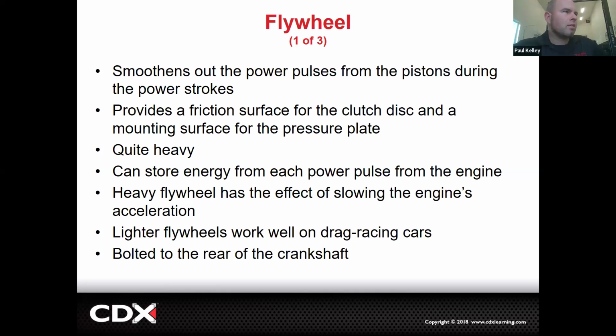And then yes, the heavy flywheel will make it so your engine will be less likely to stop spinning slowly. A really good example of that would be dirt bikes, motorcycle stuff. If somebody wants to go on these tight, small trails where you're having to bog out and go kind of slow, some people actually put heavier, they'll call them weighted flywheels. That way the engine's less likely to stall at really low RPMs because it's got some more momentum. So we will manipulate flywheel weight to make it feel a little bit different.